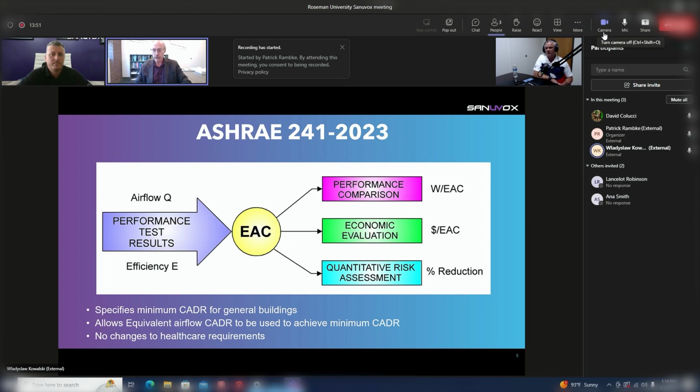It can be very effective. And modern UV systems, modern applications of UV are also highly effective. For air disinfection, we're typically looking at 99.9% reductions, verified and certified by EPA testing. For surface disinfection, we rarely see less than 90%, typically 99% surface reduction. Surface reduction systems, if well designed and properly applied, can greatly reduce surface contamination. And this includes equipment, hospital equipment, cell phones, or anything, even respirators.